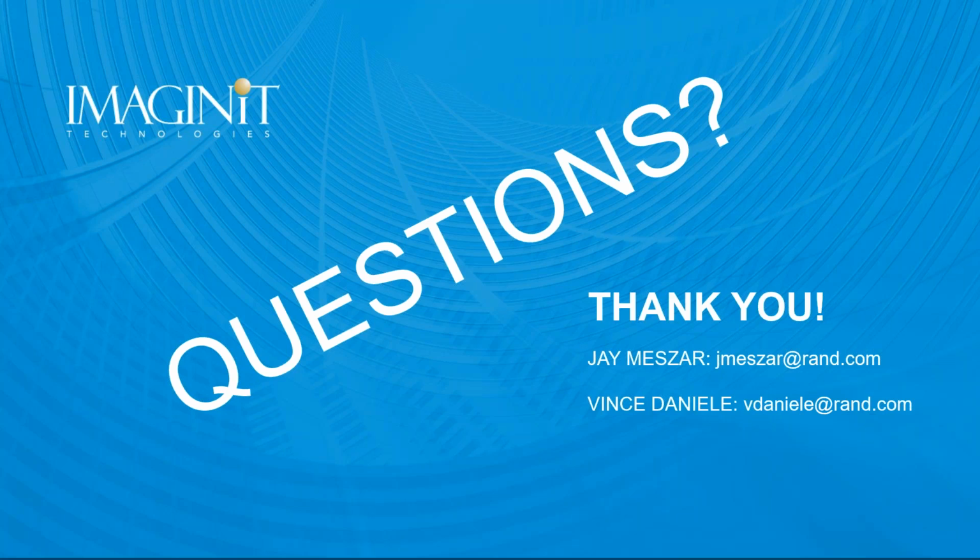So one thing I like to do, for the sake of visualization, is this: one great thing about photogrammetry is that it is creating that nice image that we can overlay on the surface. So we can kind of cheat a little bit. We don't have to have that super dense mesh. So what I like to do is take that raw data, and like Jay mentioned, we can create the mesh from Pix4D or a number of other programs using photogrammetry techniques to create that mesh surface. Bring it into a mesh editing program like 3ds Max, and I'll just use it as my background